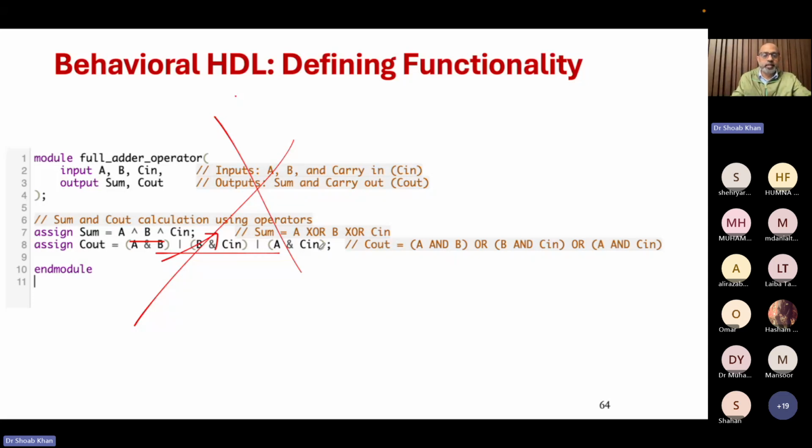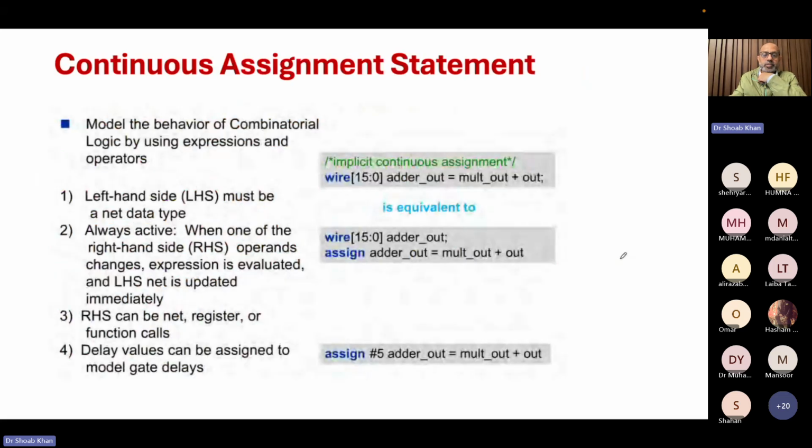You don't need to figure out how a sum works. You don't want to make truth tables and find out how the sum and carry out of an adder would look. So if we are going to use an operator, we use an assign statement. This is called a continuous assignment statement. It starts with the keyword